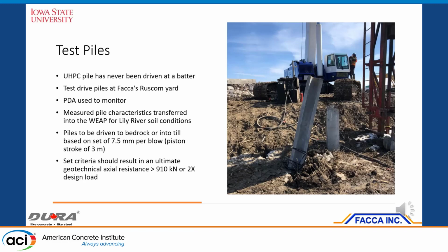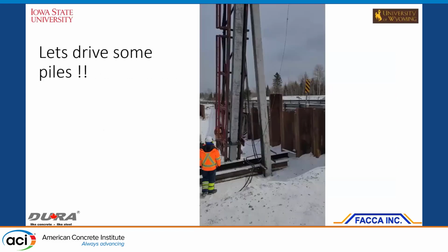You can see here, we drove it using the regular pile driving machine for H-piles. We had a geotechnical engineer locally come and do the PDA test and give us the set criteria, all that. So we are ready. We have the test, we have the results. Owners are happy. Let's go drive some piles.